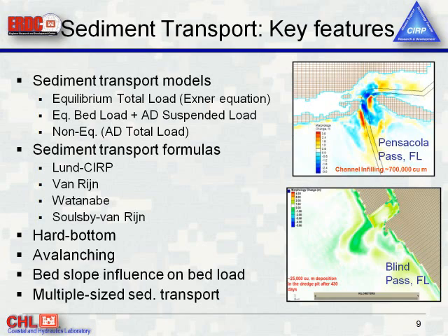Sediment transport, we have 3 models available. The classic external equation, which is the equilibrium total load model, an equilibrium bed load plus non-equilibrium suspended load, and a total load non-equilibrium transport model, which is the new one. And we've had really good success with that one.